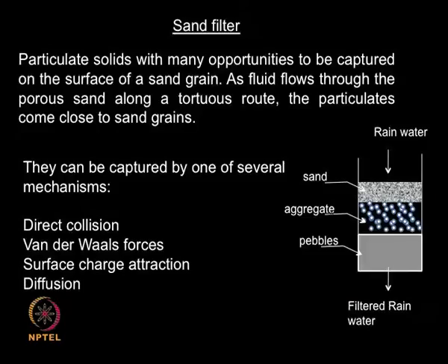Number 2, the amount of solids present is minimal, because if the amount of solids present is very large, then over a period of time it will block the entire filtration assembly, because here you are not going to collect the solids, they will be captured at different places. Some solids depending upon the particle size may be trapped in the sand, some may be trapped in the pebbles, some may be trapped in the aggregate. So these filters are useful generally for rainwater harvesting or water purification facilities.